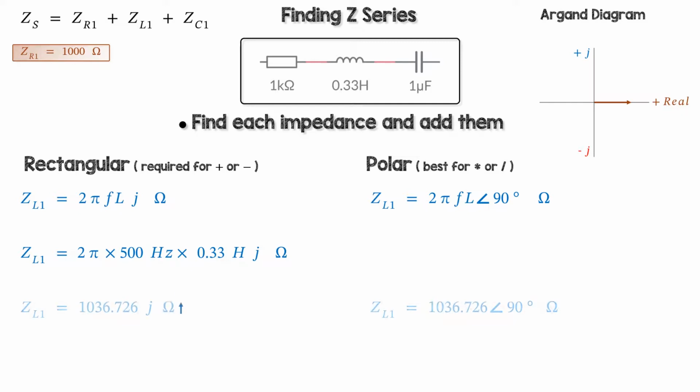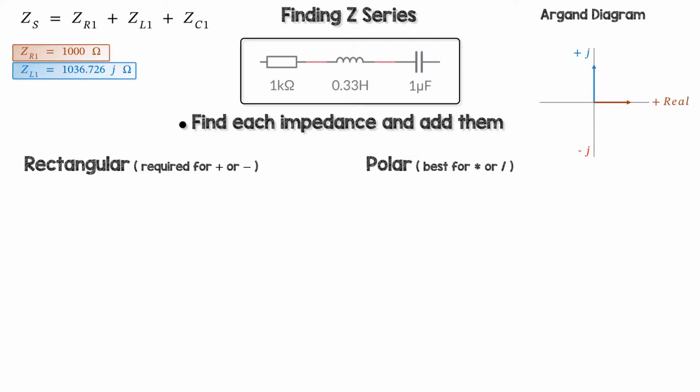This reactance or impedance is purely imaginary in an ideal inductor, so it has no real part and lives at positive 90 degrees to the x-axis, as in pointing north. Capacitive reactance XC also opposes current and equals 1 over omega C, or 1 over 2 pi FC, where C is the capacitance in farads.